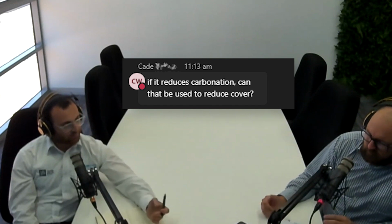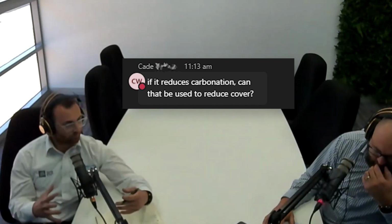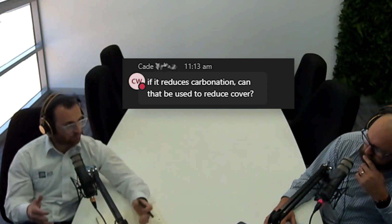So I was going to say, you mentioned the exposed reinforcement. We can actually halt that deterioration at that point, and then work in with remediation specialists to fix it. And we effectively double the amount of cover. So if you've only got 20 mil of concrete cover, by us incorporating our CivilTech systems, you're effectively doubling that level of cover. Really cool question there, and it does come up a lot.